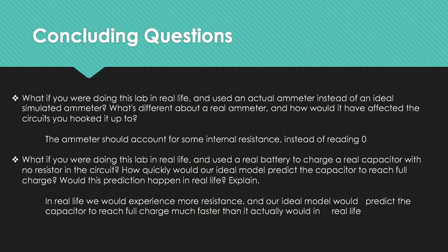And lastly, more concluding questions on the lab. What if you were doing this lab in real life and used an actual ammeter instead of an ideal simulated ammeter, and what's the difference in these two situations? I said that the ammeter should account for some internal resistance instead of reading 0, so this would alter the values that I got previously.